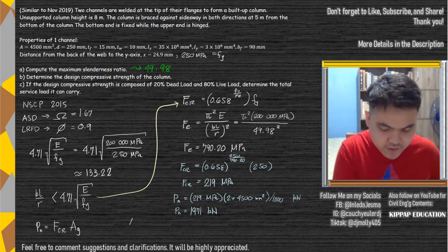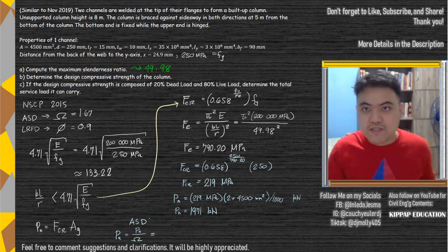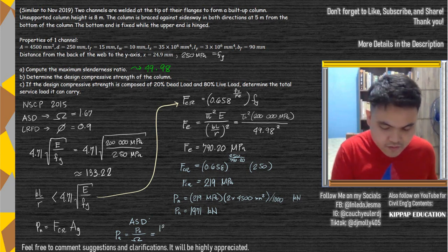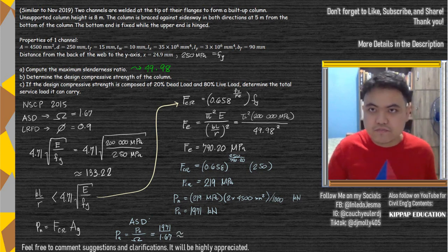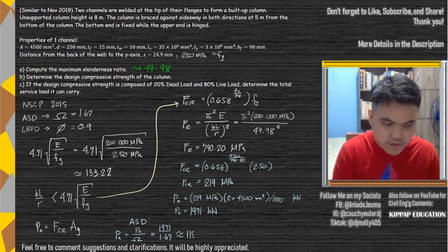So, let's try ASD muna. So, P sub A or P allowable is equal to P sub N over omega. So, yun lang. 1971 divided by 1.67 is equal to approximately 1,180.24 kilonewtons.